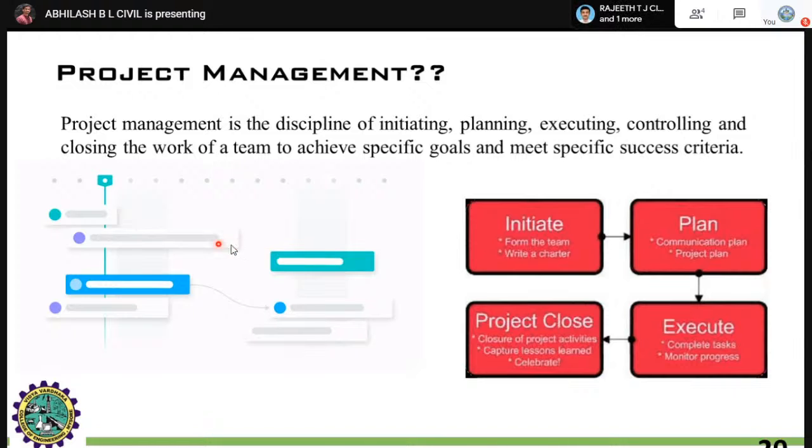For example, after the construction of openings and masonry units, later on you have to go for the lintels and chajjas, right? Similarly, these works should be planned. While doing the masonry part, why should you sit empty, right? In order to make the human resource work efficiently, you can go with other activities such as flooring and finishing parts.